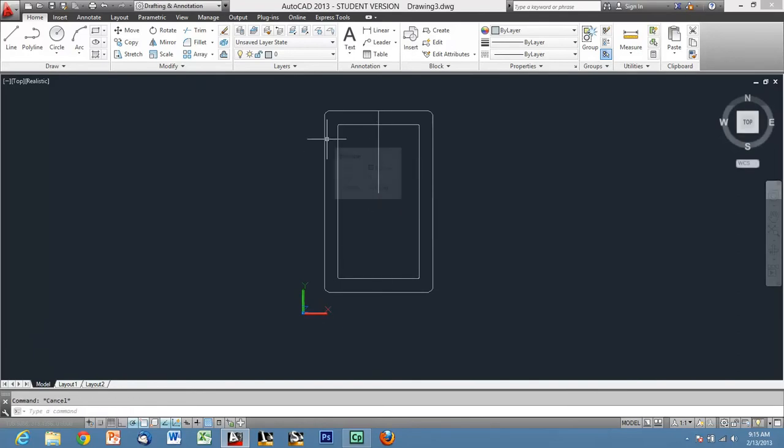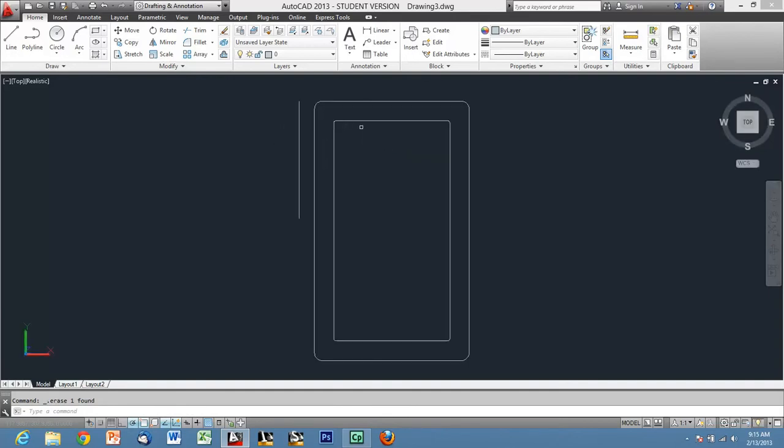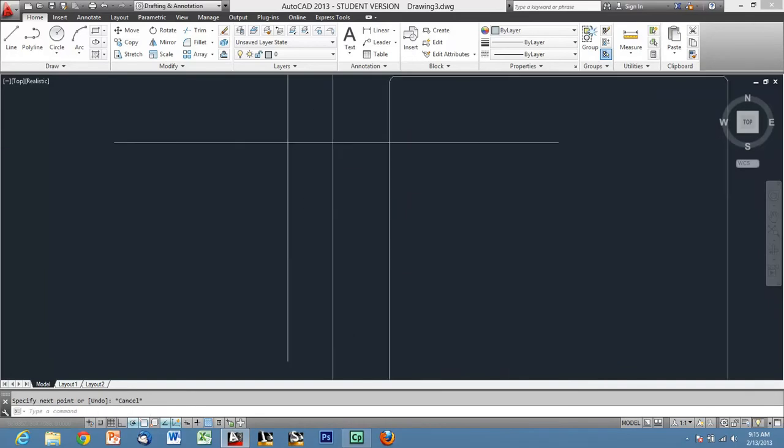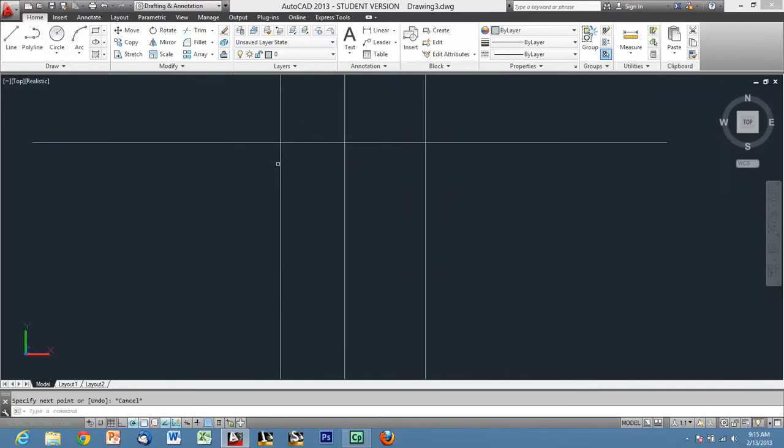The first tab should be 120 millimeters over off of this. So I'm going to use the offset tool at 120 millimeters and just come over here to the left. And then off the top, I know that it's 54 millimeters down. So right there we have the center line of the tab, and the edge of it should extend over to here.